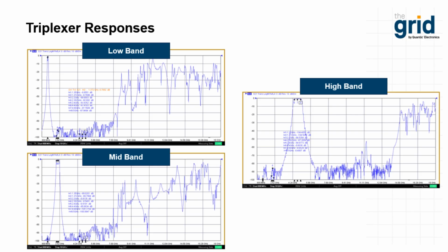The low pass filter can have a much gentler roll off because you're discriminating from something that's very low in frequency versus something that's very high in frequency. So you have a lot of room to get the rejection down, and the insertion loss can stay very good, even though it's an LC filter. LC filters are actually kind of perfect for cleaning up things like this because they tend to not repeat over frequency.